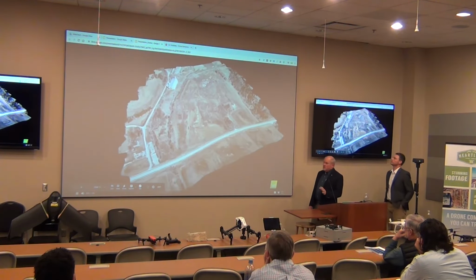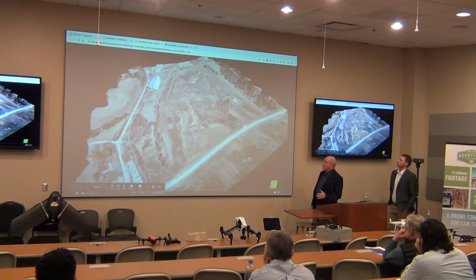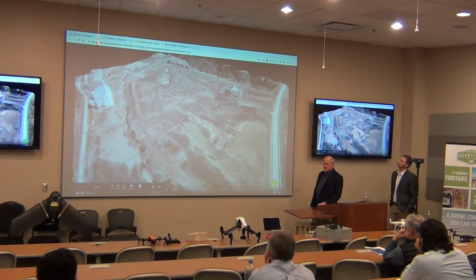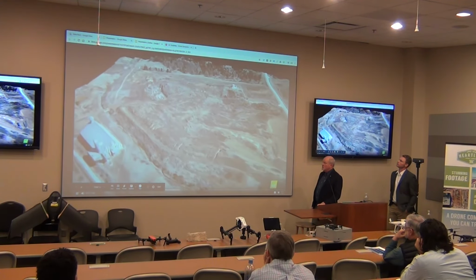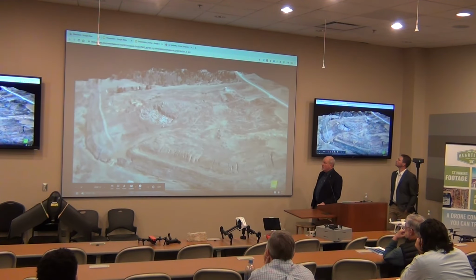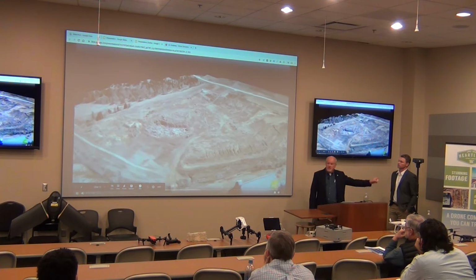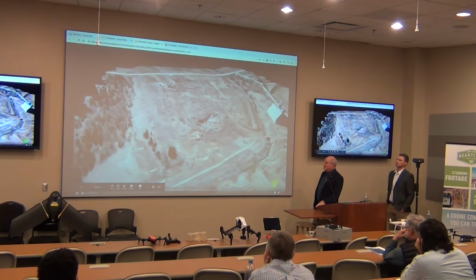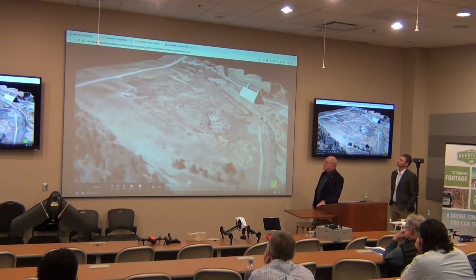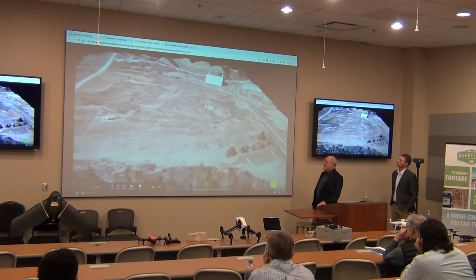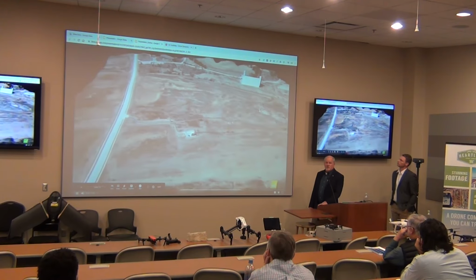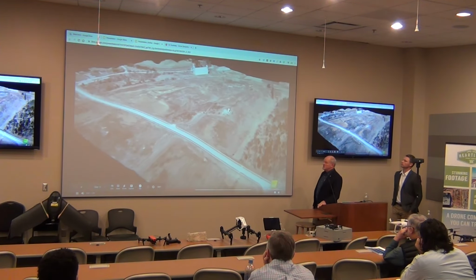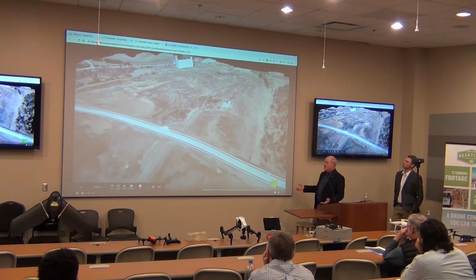So that area was technically surveyed by the drone. It was the DJI RTK Phantom 4 working off of the D-RTK base over a known position. Accuracy is 3 centimeters. Resolution is 1/2 inch. This is actually an animation of the point cloud, and I'm just pretending like I'm the drone. So this is post-processing. The drone never actually flew this path.